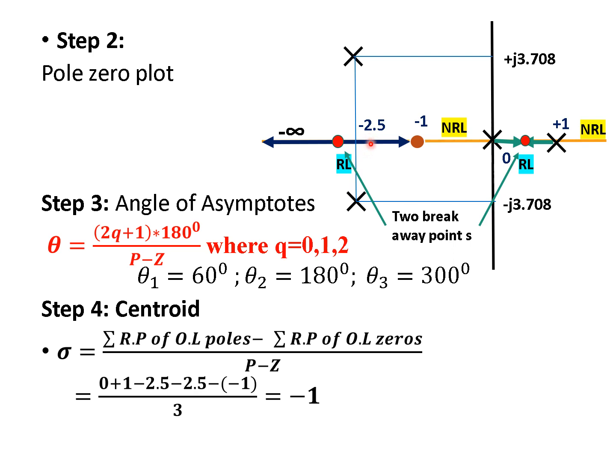So the total is odd, which is 3. So the root locus exists from -1 to minus infinity. And one more important thing that you need to observe is the breakaway point. As we saw in earlier problems, whenever there are two poles, we are sure that there will be one breakaway point here. But in our case, there is one more breakaway point between -1 and minus infinity.